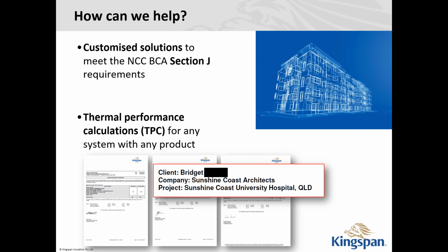When you calculate the thermal performance calculations, do you consider ventilation? Ventilation, yes, we do. Depending on whether the floor area or the roof area was ventilated, we'll either have a non-ventilated roof cavity or a ventilated roof cavity.